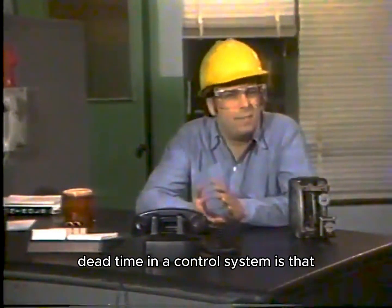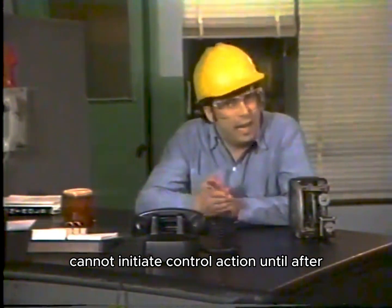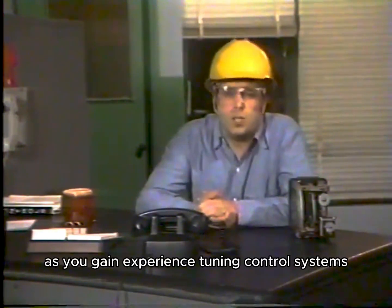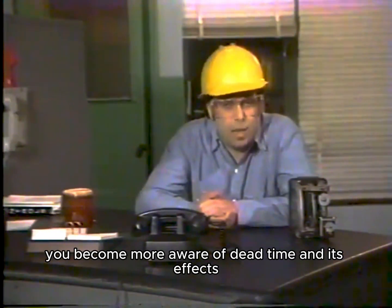The main problem with dead time in a control system is that the controller cannot initiate control action until after the change has been sensed. In some systems, this delay is critical. In others, it isn't. As you gain experience tuning control systems, you'll become more aware of dead time and its effects.